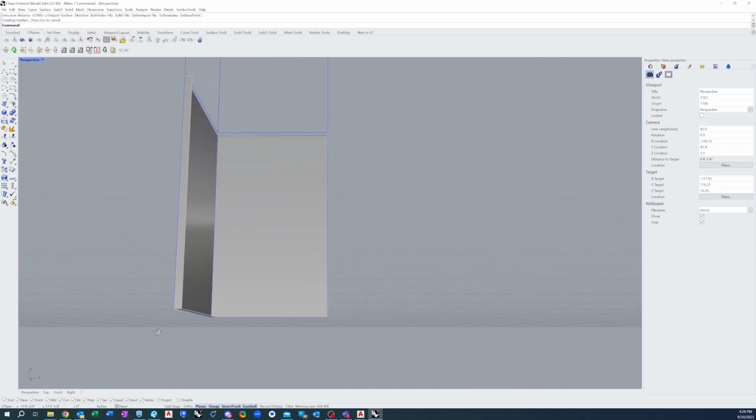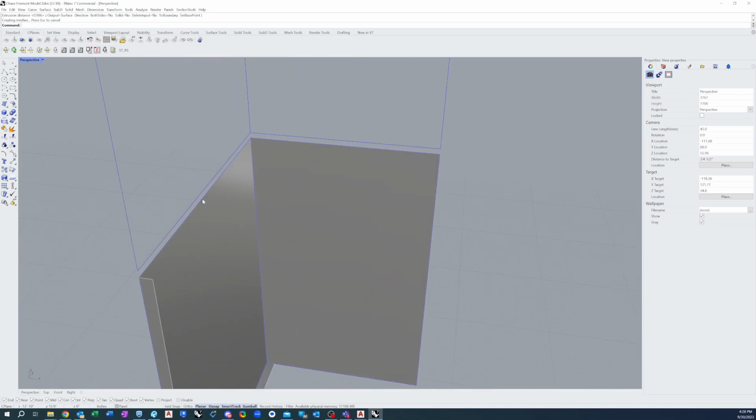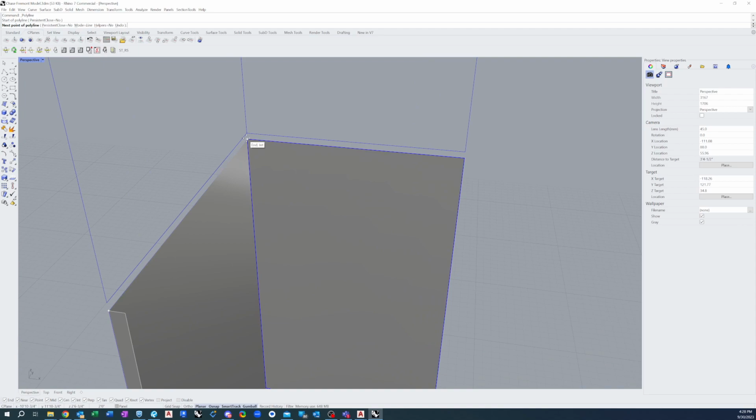Now that one's added. I'm actually going to do the one on top here so that they'll stay in the right direction. So polyline. And once you get some of these made, you can save them as templates, and then it's easier just to add them in. Extrude curve command, this curve, right click enter and direction.